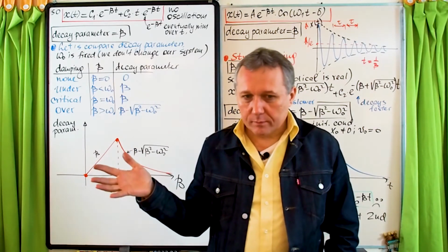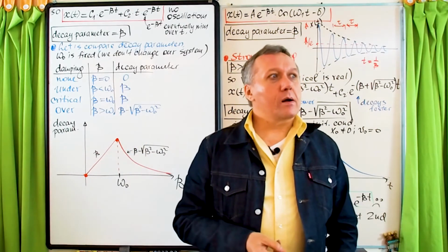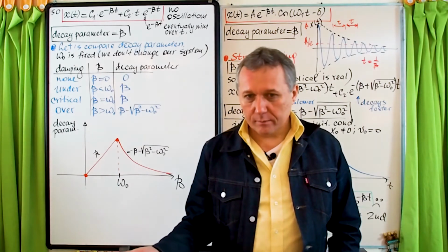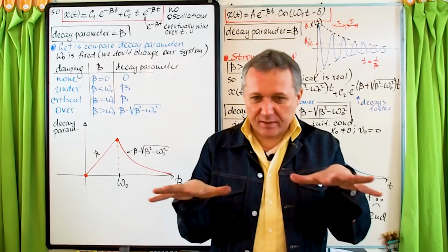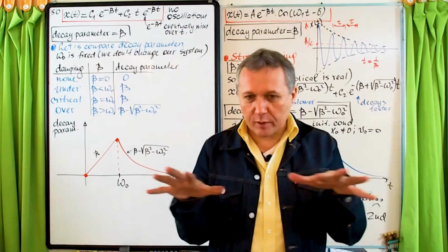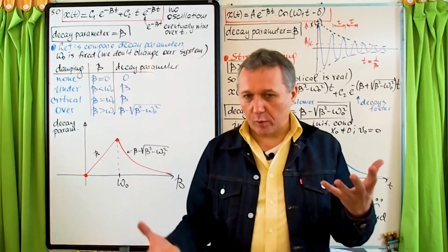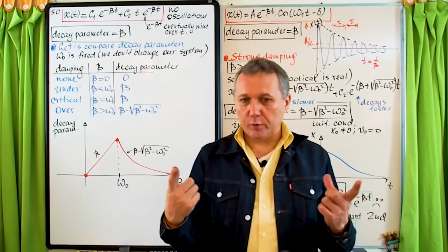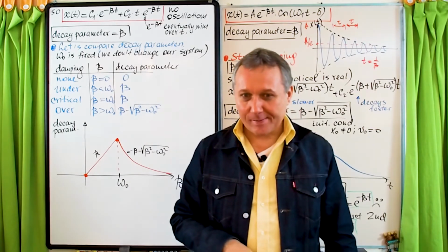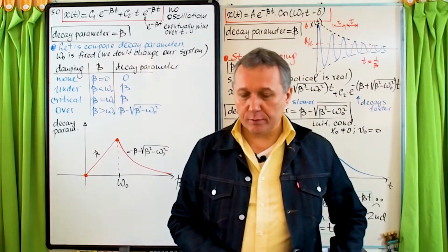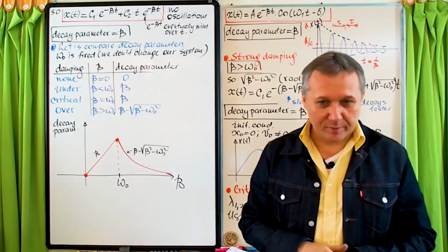Then another example, again in the lab. For example, let's say you use a spectrometer. Let's say, like in my case, we measured the spectrum of a laser in a pulsed mode. In that case, the spectrometer must be as stable as possible, without experiencing any oscillations or vibrations. Usually we float the optical table, so there are 4 pneumatic legs, and as a result the table is like in the water. Again, the same critical damping is used. If you displace it slightly, then it goes back to the equilibrium as fast as possible.